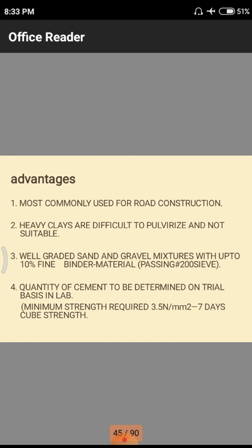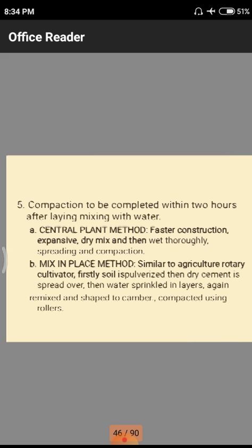Normally, concrete cubes are tested for 7 days, 14 days, and 28 days in the form of curing. That means for 7 days we have to cure the member. After that only we go for the testing. In this testing, we observe the strength possessed by a member. Here also we follow the same phenomenon, and we need a minimum strength of 3.5 Newton per mm square.